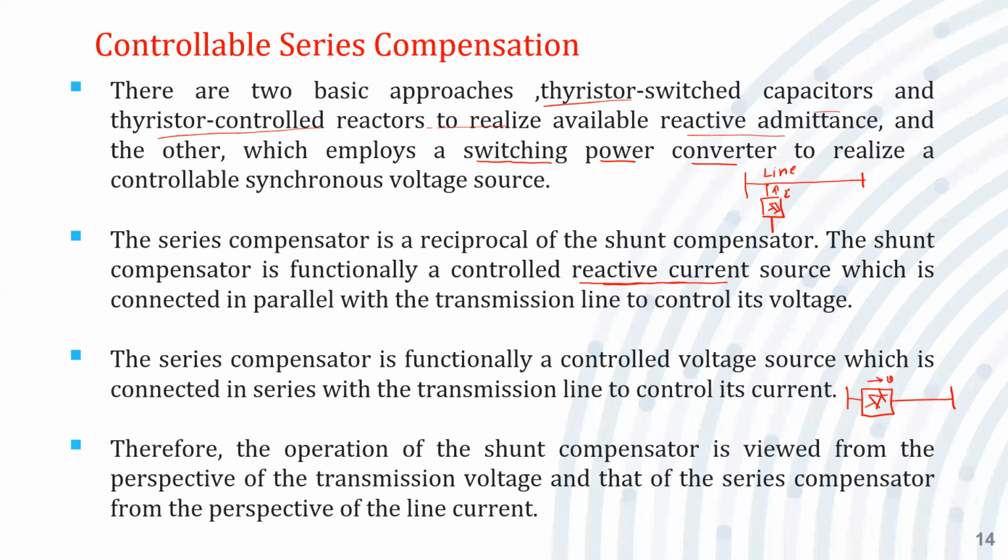And next point, the operation of the shunt compensator is viewed from the perspective of the transmission voltage, and that of the series compensator from the perspective of the line current. So these are the two differences between shunt compensation and series compensation. In the next lecture, we will see the controllable series compensation, the procedure, and how to control the series compensator in the transmission line.